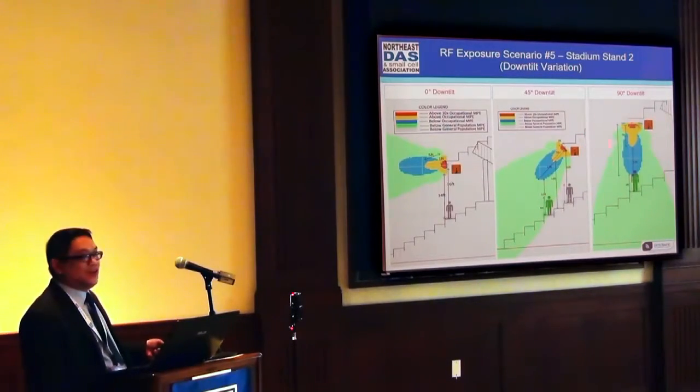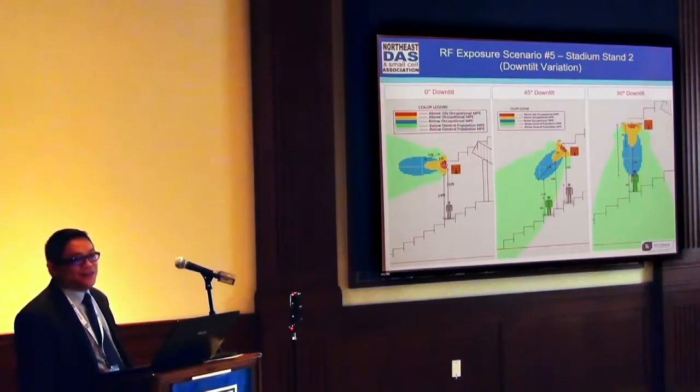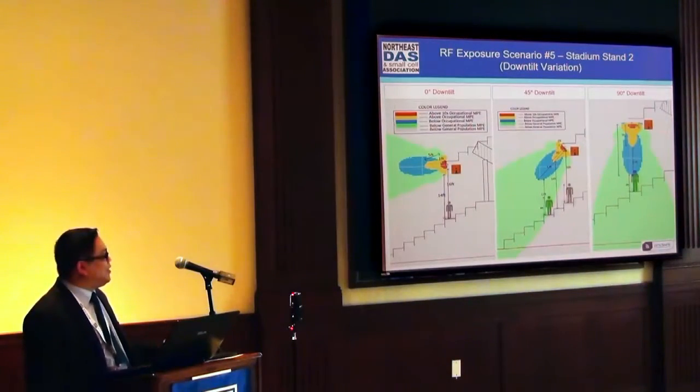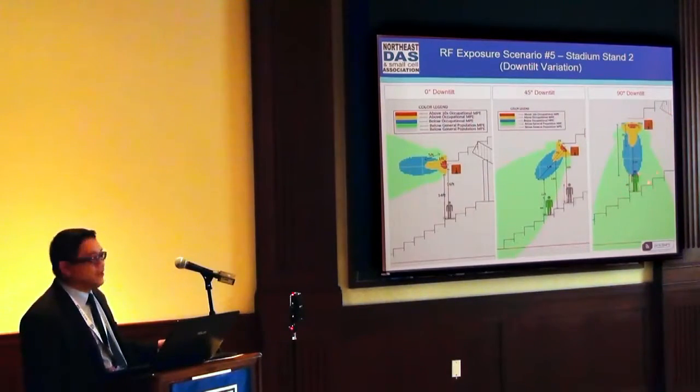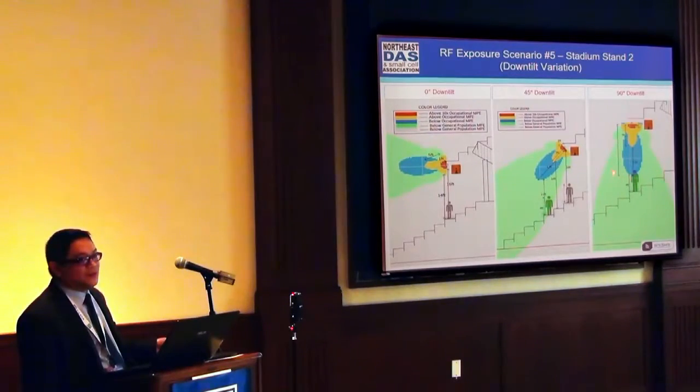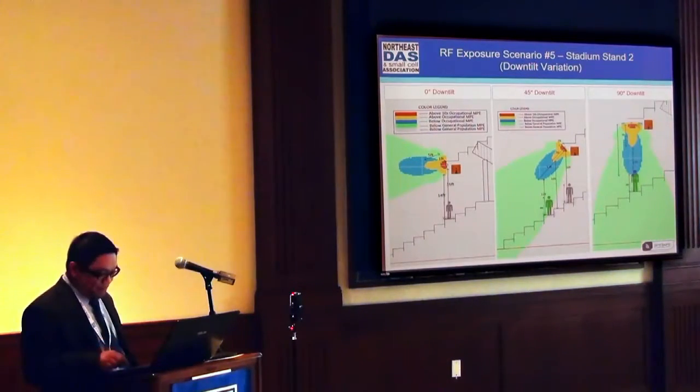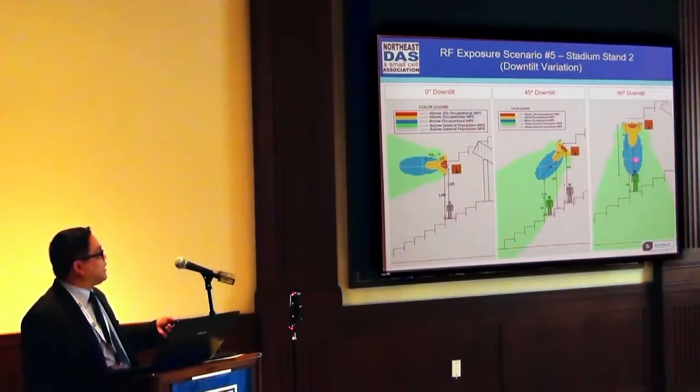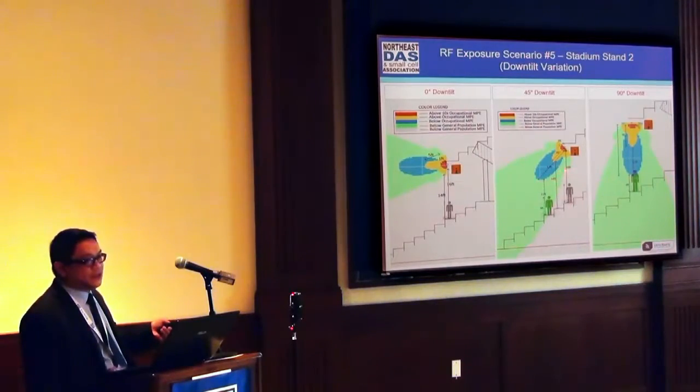Now, what's the impact really on this? You would just feel hot. By the time you get out from underneath the antenna, you would be fine. The problem is, if you get too much exposure, if you're there for hours sitting underneath the antenna, that becomes a real problem. So again, it is important that when you're doing your design, you have to consider RF compliance, because there is a possibility that you would fail.